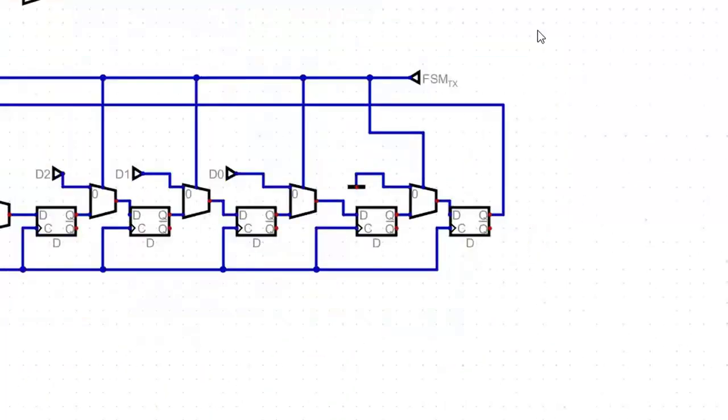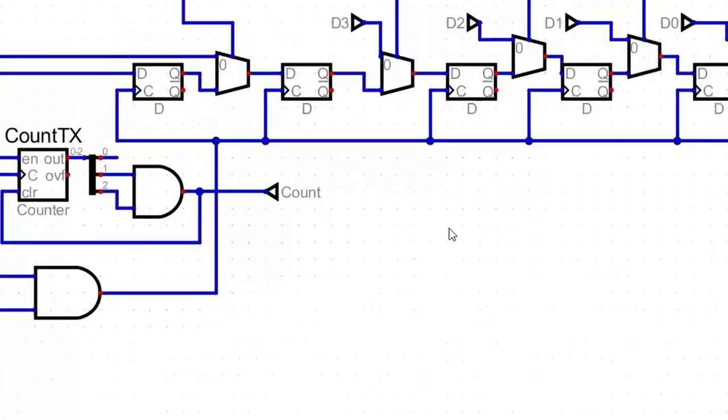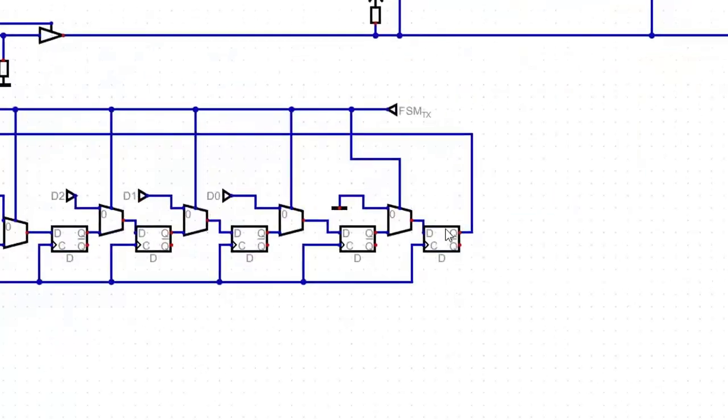So what I think is wrong is that if there's a 0 here and needs to go from this line all the way to the serial line, then it needs to go with this clock. It has to be first clocked into this flip-flop and then it has to be clocked into the serial line.